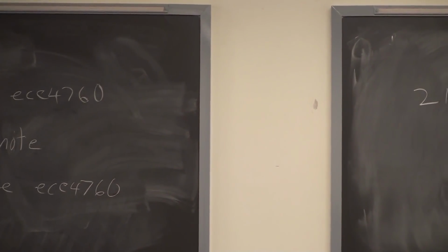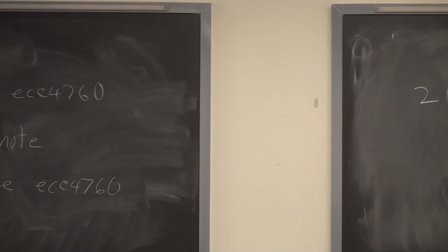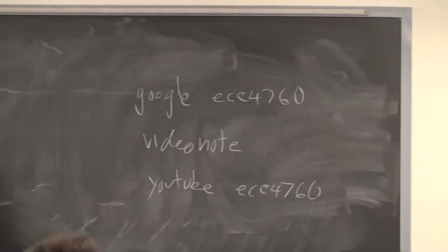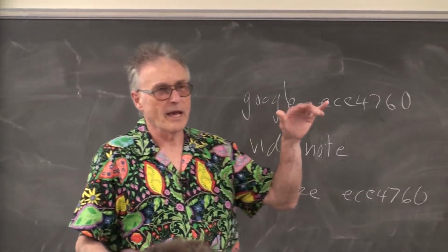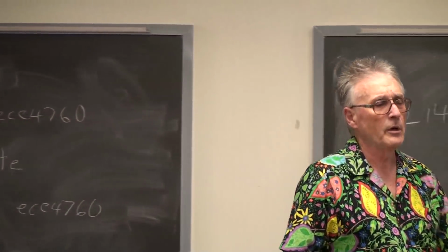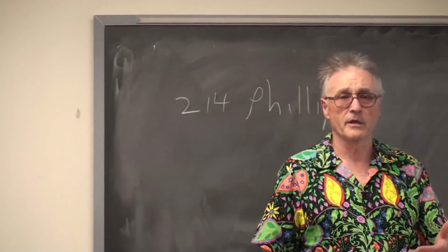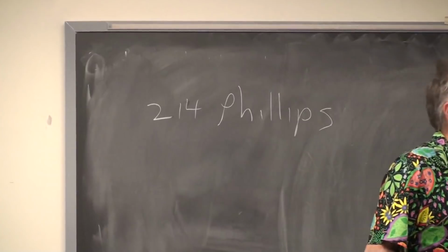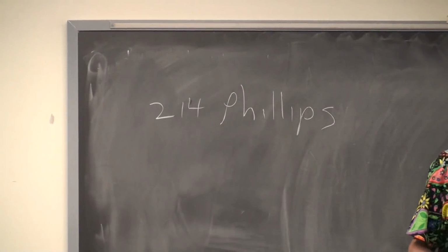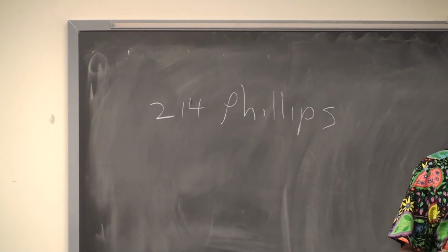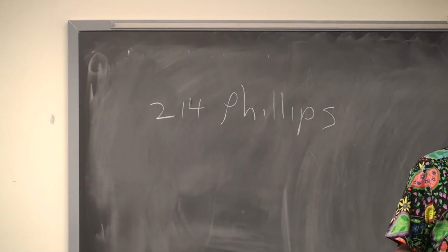For instance, there's timers. Every timer is a small coprocessor that has a very limited instruction set. It knows how to increment, it knows how to compare, and it knows how to toggle certain I/O pins. There are much more sophisticated peripherals on this chip, including serializers and deserializers of various sorts, but also so-called direct memory access peripheral, which is a bus master just like the CPU. It can issue bus commands just like the CPU.